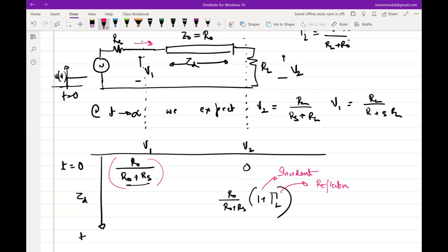If you want to put that, what you can assume is that there is a small stretch of transmission line after RS, which is matched to RS. And then you are going to have a reflection between that transmission line and the actual transmission line, and you can then go about doing it. So that's why that lumped element approximation is important. If the transmission line goes to almost zero, there is no forward going and reflecting, and a reverse going wave. So whatever happens instantaneously. Okay. But good question. Fine. So now there is a reflected wave at V2.